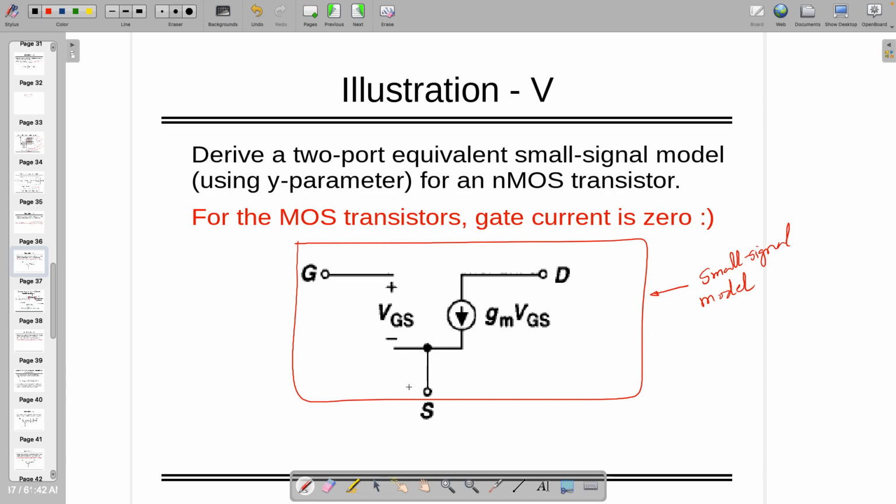Now let's go this way. What is the impedance looking into the gate terminal? Infinite. Into the drain? How much? Infinite, right? Because there is zero current. So infinite impedance. Through the source, what I'm saying. By the way, VGS was 0, that's why gm was going 0. Okay, those who are not able to see. So from the source, 1 by gm.